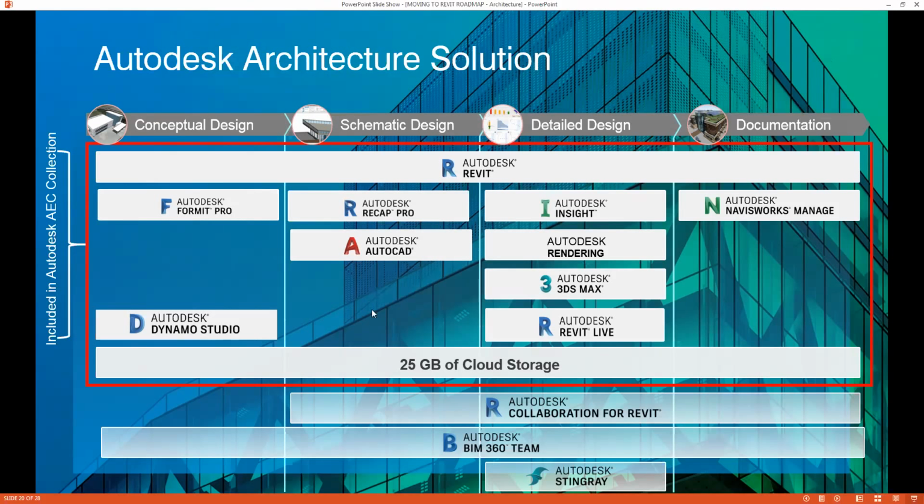Schematic stage. Now, you have your broad concept. Now you're working on the schemes, like, what's the relationship between spaces? Should the living room flow directly to the kitchen, or should we just put a wall there? What should be the circulation? What's the interaction between circulation and private areas and public areas? We are working with schematic design here.